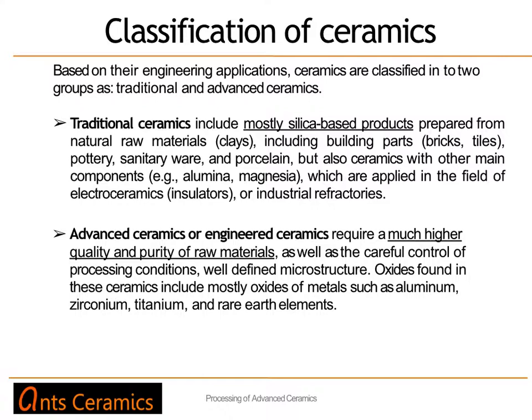Based on the engineering applications, ceramics are classified in two broad groups: traditional ceramics and advanced ceramics. Traditional ceramics are those which are mostly silica based components or prepared from natural raw materials, like bricks, tiles, sanitary wares, porcelains, and also ceramics with other components like alumina and magnesia, which are used in applications like electroceramics, insulators or industrial ceramics.